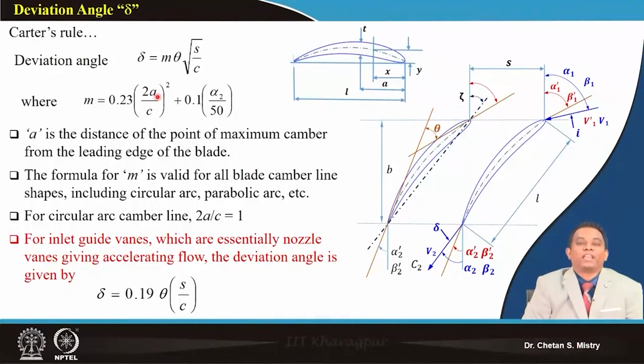So today we have discussed how we move with the change in incidence angle, and what parameters affect the incidence angle. We have realized that mass flow rate, speed, Mach number and Reynolds number are the flow parameters changing the incidence angle.